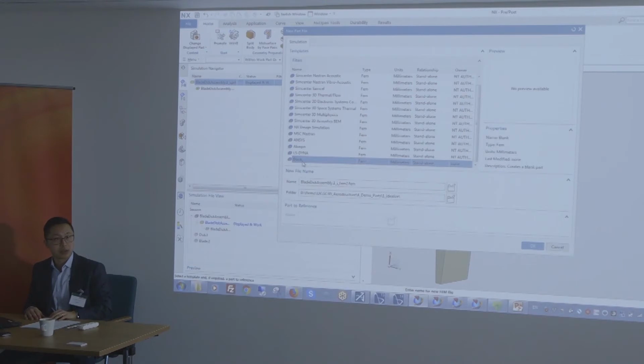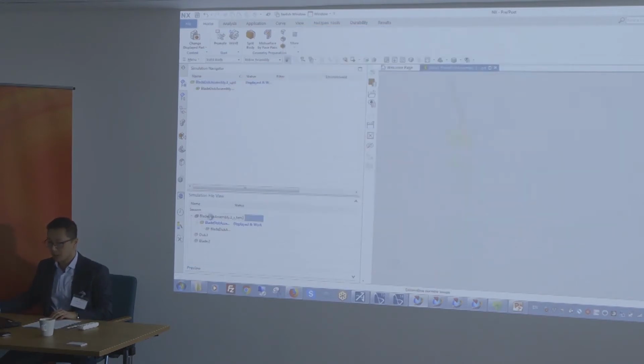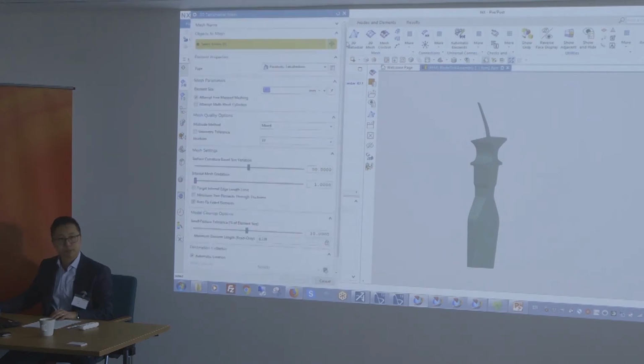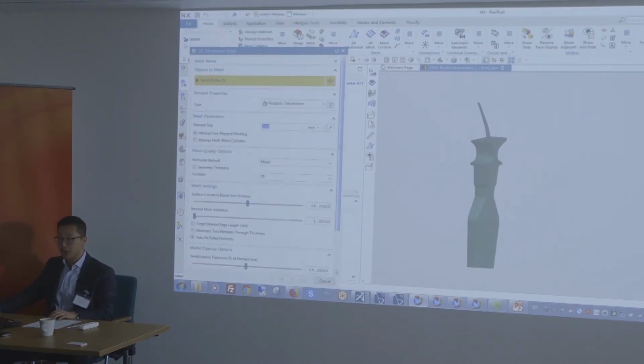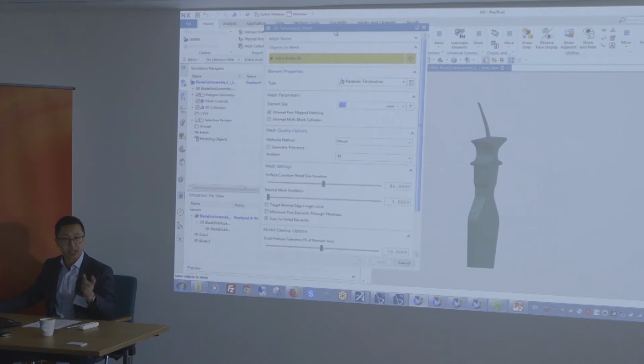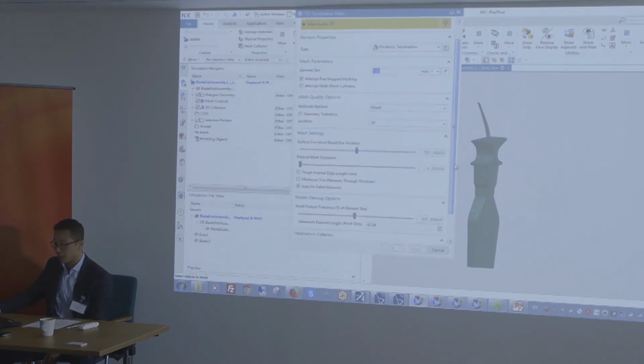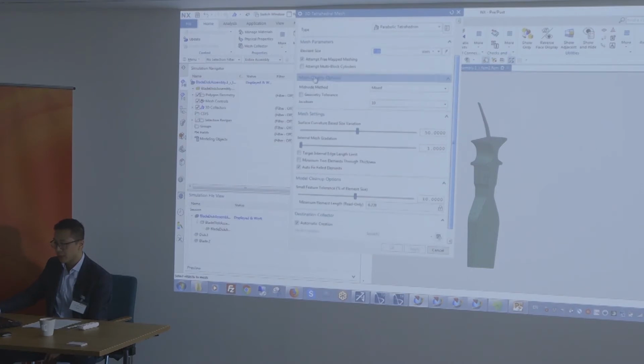Quality, could you put in specific quality checks, relevant quality checks? Yes, yep. So if I go here, as part of that template, actually when defining the mesh that points to that selection recipe, we have some advanced options here that I'm just going to expand. So in terms of the mesh quality, right? You can specify a certain tolerance, Jacobians, depending on where you want to put the nodes. All of these here can be adjusted beforehand before creating that.